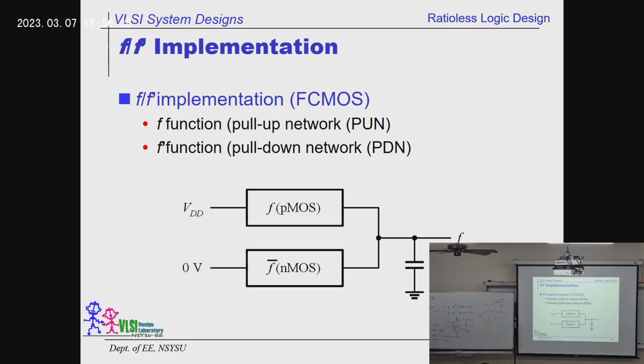Then you are going to have almost a perfect design for this NOR gate, because after our rough calculation, all you have to do is increase the width of the PMOS devices on the top. Then you are going to have about the same charging time, just like we had for the inverter. Is that clear? Really easy, right? Even undergraduate students, even elementary school kids can follow the same rule.